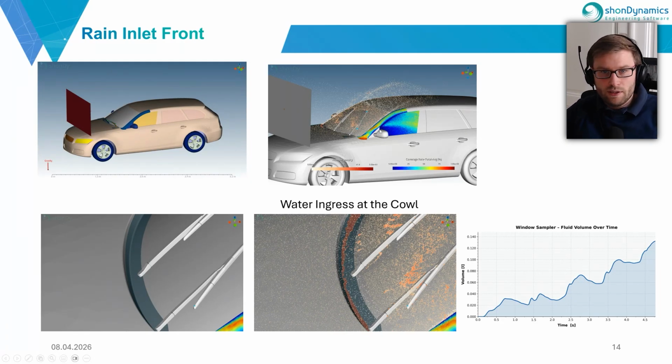And then you can also compare how the fluid distribution looks like in this kind of setup. So you have a wind shadow of the mirror. This protects more or less the fluid from hitting the sidewall, but then you have an accumulation on the A pillar of this fluid, and then from there to the side window of the driver seat.